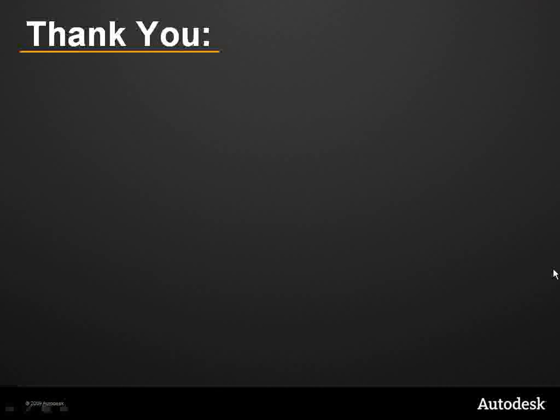So you could be in a UTM, and you want to say I'm in UTM Zone 15 in the header. So when you bring the data into the active DWG, it interprets it and knows it's that. It's just like the survey database. It will convert it to the active DWG unit settings. I know that's a complicated thing I just said, but it's actually very simple. And it's in the online help how to do that. I hope that answers that.